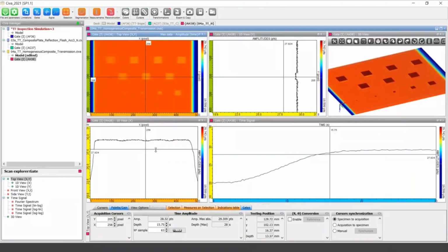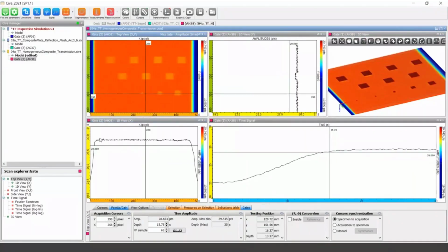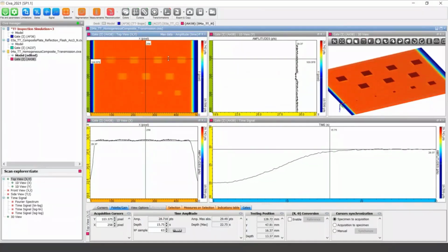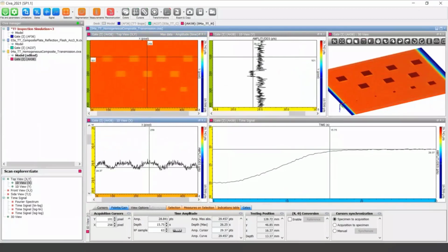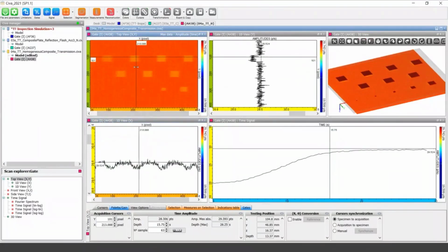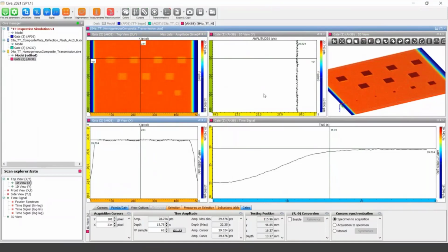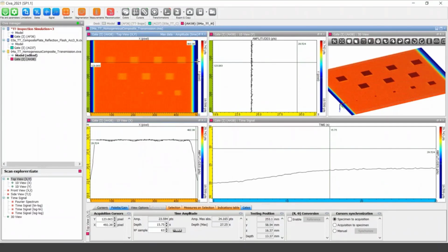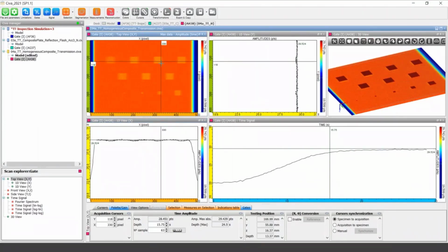You can also see here the contrast with the cross section and the profiles, to see what you can have in terms of contrast. And so we have a bigger contrast, of course, with a large defect. And you can zoom in to evaluate a little bit the contrast in temperature between the defect and the defect-free zones. So you have 2 profiles versus X or versus Y, sorry, that can be analyzed. Here, I'm out of my object. So in this case, I can quite properly detect most of the defects, except maybe the 2 smaller ones.